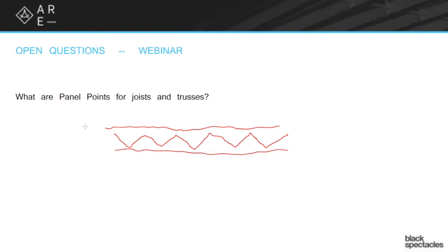So the whole point of any type of beam really is span, and to get span, what we really want is depth. That's how you get stiffness, that's how you get the capacity to span longer distances. While thinner, less deep material can span pretty far, depending on if it's steel or certain kinds of wood, the game is always, can I get more depth compared to the amount of weight of steel, or compared to how big a tree I would need, et cetera. And so the truss is the way that you get that.